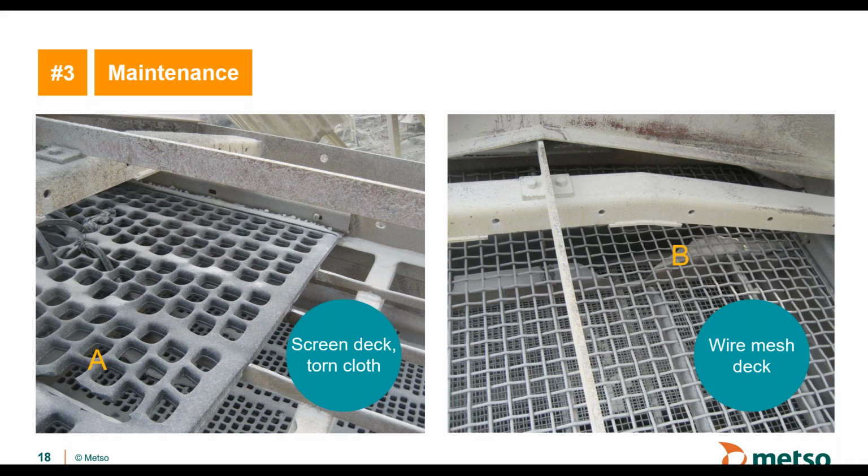So this is the case because the stringers are worn, so it's impossible to tension the cloth. So to come back, you need to replace the stringers, you need to replace the rubbers and a new cloth, and then make sure that it sits tight to the cloth, and then this will not happen.